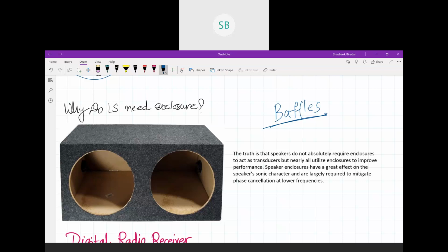Okay, there is another concept which is called a multi-speaker system. You can use various types of loudspeakers for various purposes, but still, so as to enhance the quality of the sound, you can have a woofer, mid-range speakers and tweeters, so that sound within the frequency range of 20 hertz to 20 kilohertz is listened to properly.